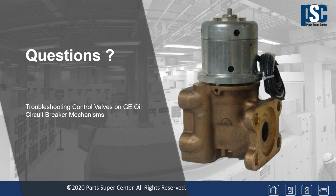Similar question. What is the best way to fix a leak at the main piston to valve body assembly? So again, this is another metal to metal seal. The piston is a bronze alloy or brass alloy, and the valve body is a bronze alloy. Once again, those are very precisely machined and then coined in the factory, but you have to be very gentle